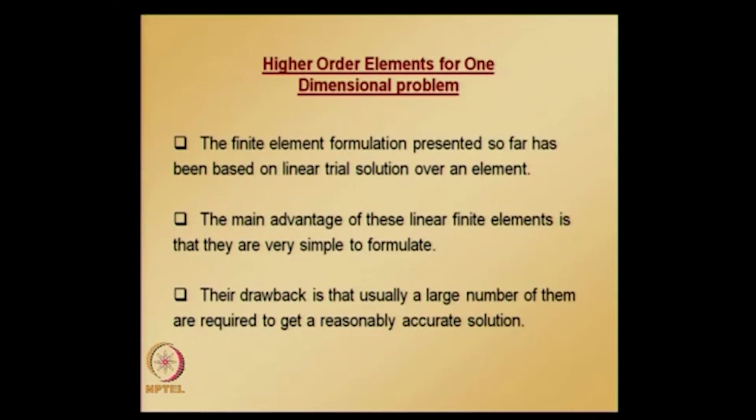to use more number of linear elements, but as you increase the number of elements the equation system also gets increased, because we will be having more number of nodes. So one way of improving solution is to go for higher order elements. So that is what we will be doing in this class.